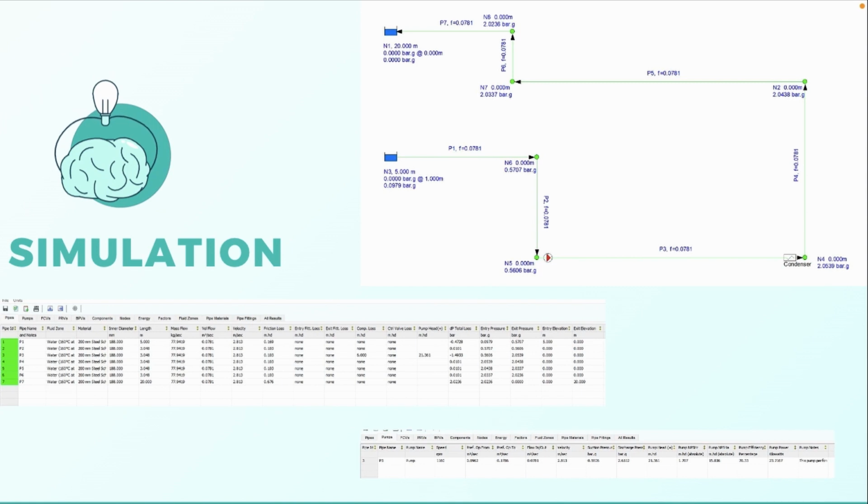Now, we will be utilizing flow simulation software to design and simulate our piping system based on the selected pipe size of 0.188 meters and the pump specification we calculated earlier. We also choose steel material for our pipe because the temperature of water is around 30 to 160 degrees Celsius. We have chosen to use Pipe Flow Expert software for this simulation.